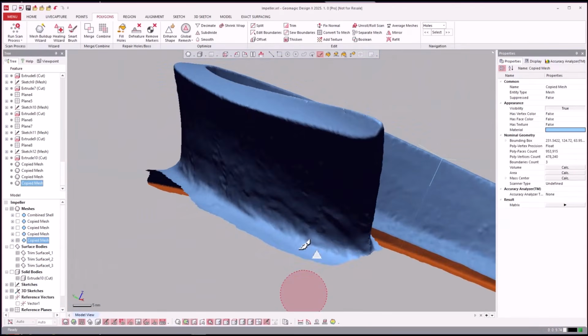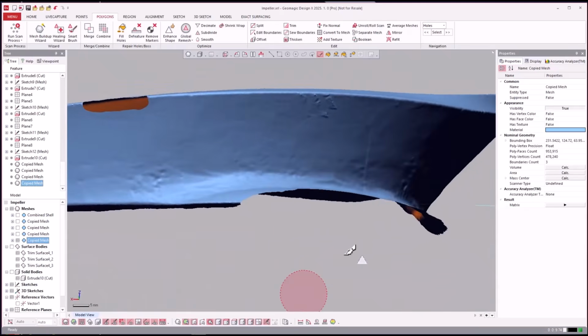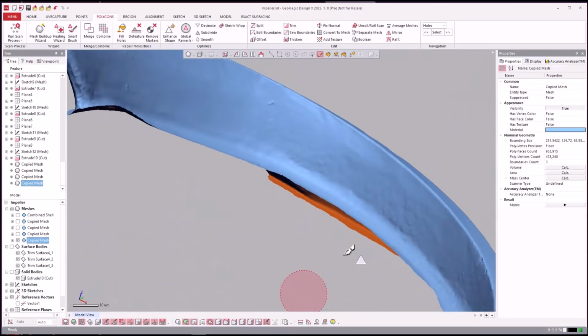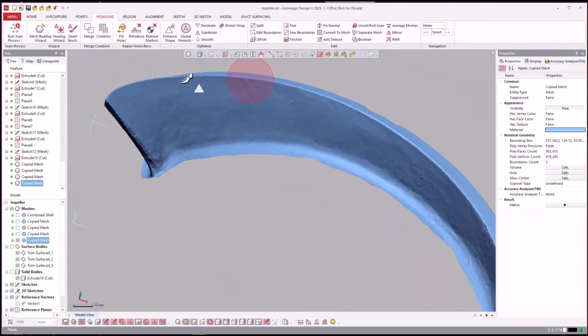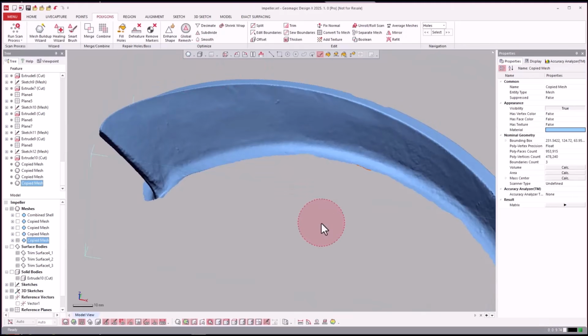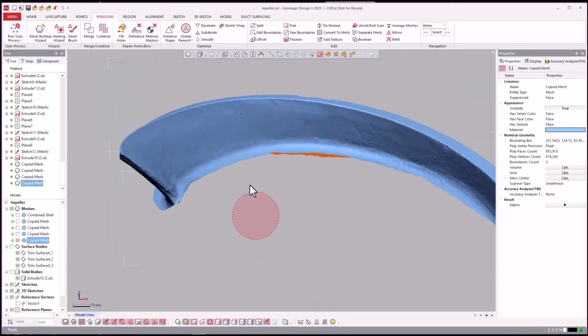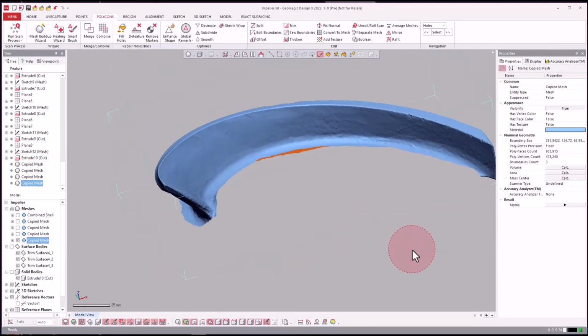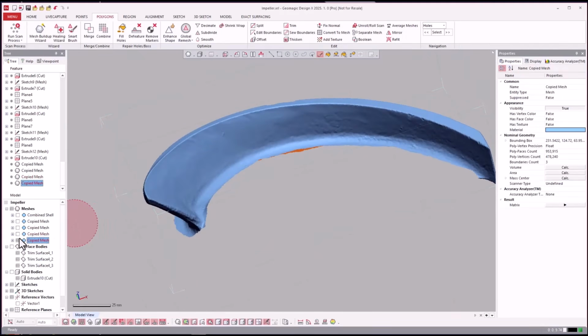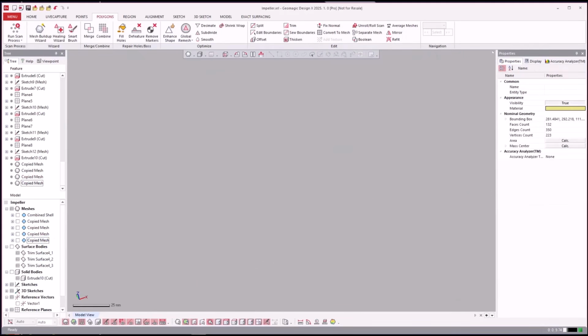So you see that? It edits it by microns, but I like global remesh and then do like a 0.5 or 0.7 somewhere in there. And then you could do that on all these too, just to clean them up, tune them up a little bit, and then turn that off. So now let's just go jump over to the averaging tool.